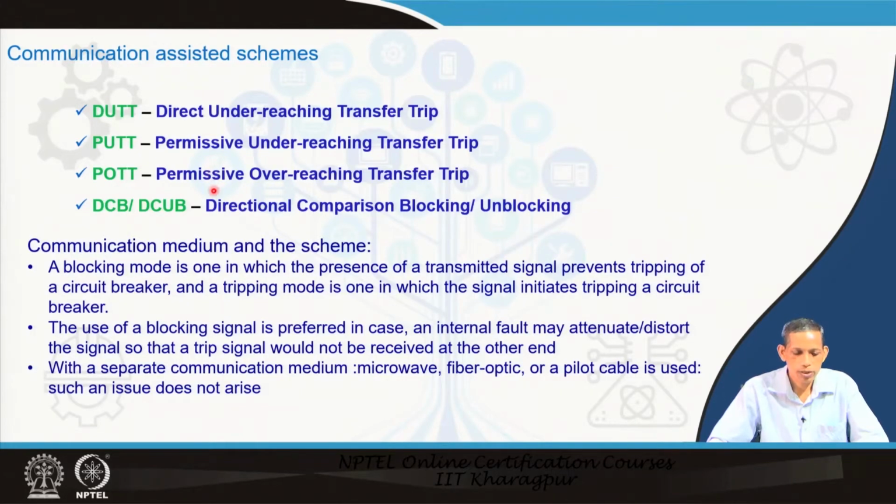The other distinction from this terminology is that it is a trip and this is a block. Whether you are transferring the trip signal or the block signal is also important. All these options of communication assisted schemes with distance relay, which we will be discussing, may require a communication medium, and based on the available communication medium, the corresponding schemes can be selected.